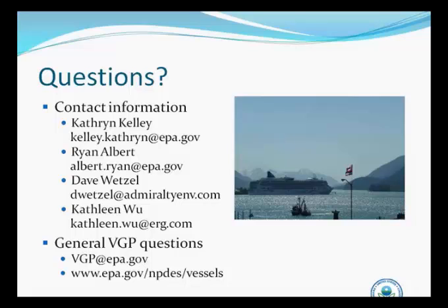And then I will immediately tie this into the next question, and I'll direct it to Kate Kelly: can you better clarify for gray water and bilge water samples who must actually conduct monitoring? Sure. So both the bilge water monitoring and the gray water monitoring requirements are for new build vessels. Well, here, I'll step back. Bilge water monitoring is required for new build vessels greater than 400 gross tons.